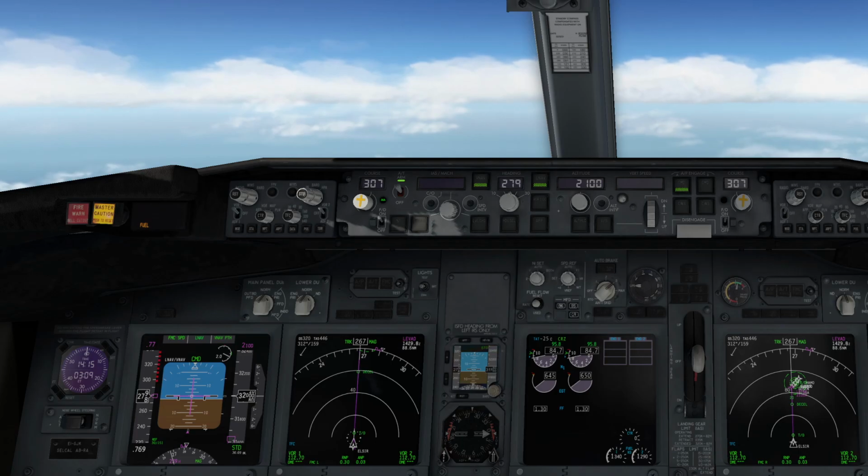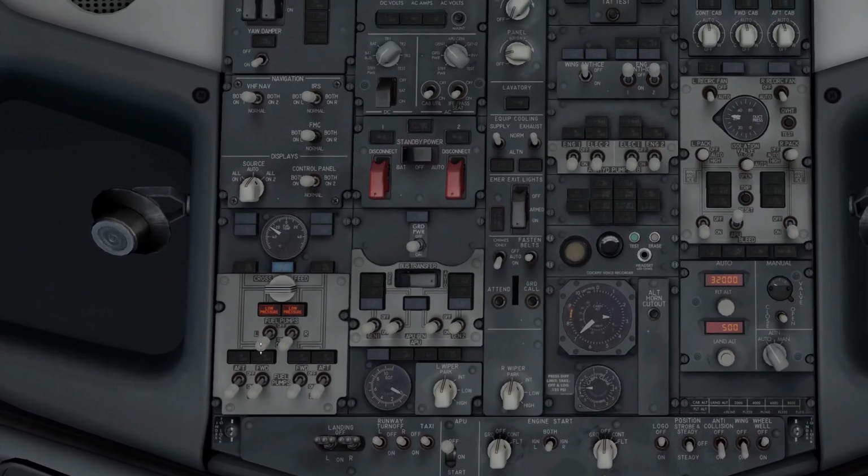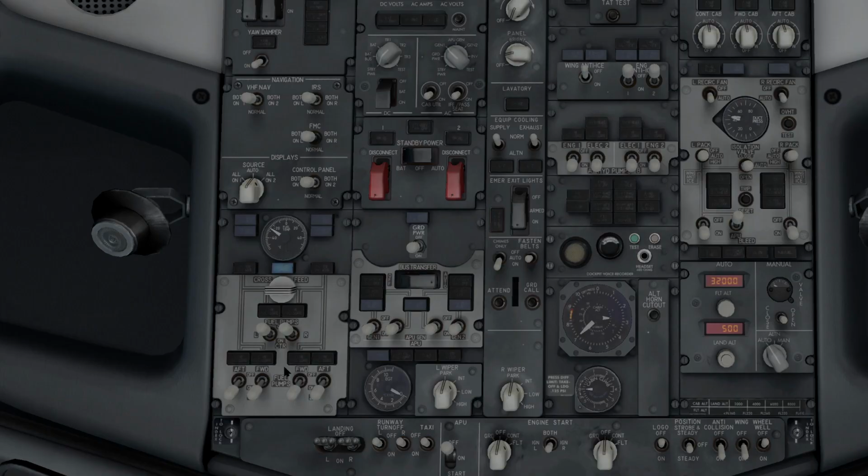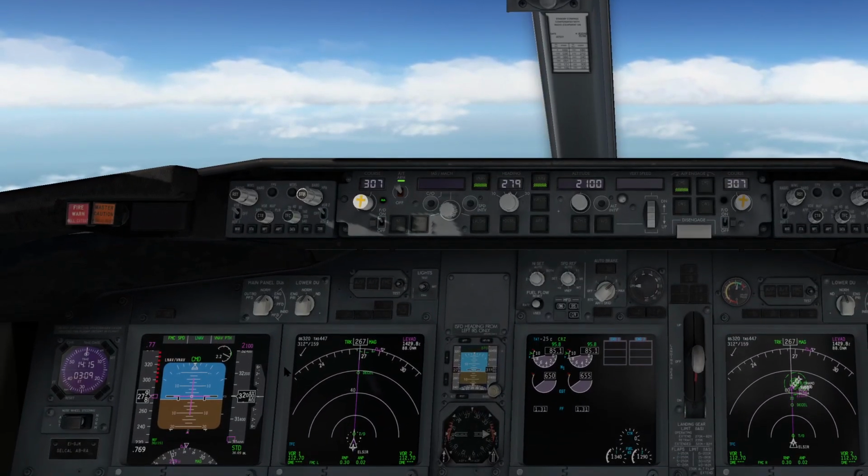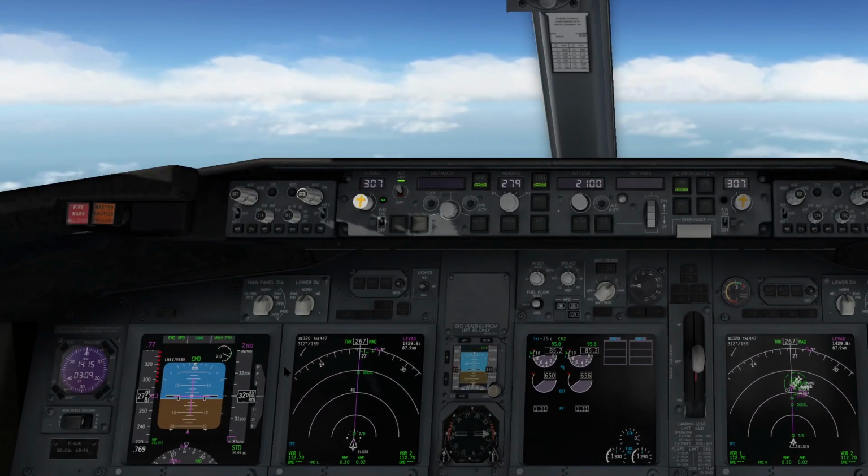And we have no fuel in the center tank, so indeed switch off the center fuel pumps. And now we should see that the two wing tanks should equilibrate. There is still a 40 kilos difference. 30 kilos now.